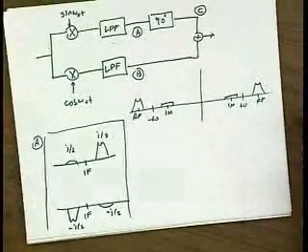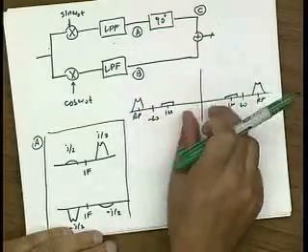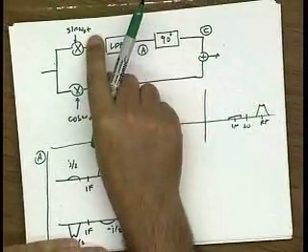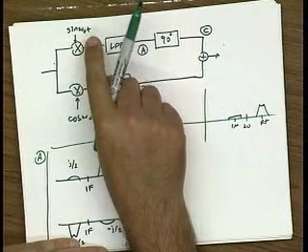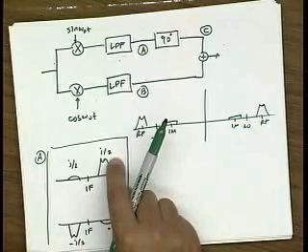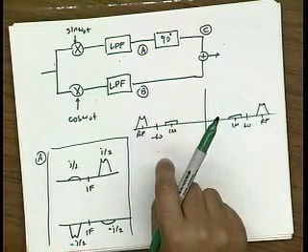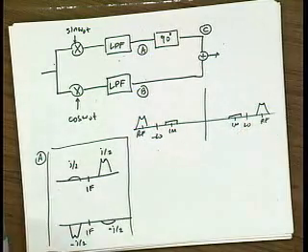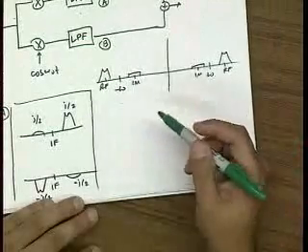Okay? So this first term corresponds to just shifting this down to IF when I multiply by e to the plus j omega naught t, right? And then there's an extra factor of over 2j in there. And the second term corresponds to this being multiplied by e to the minus j omega naught t. Okay? How about at position B?